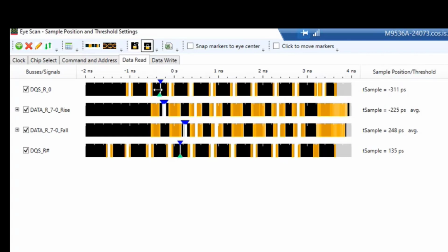This is a state measurement setup, and the strobes are going to look like a flat line in state mode since they're being sampled once per clock cycle. But they're very handy for timing zoom. You want to make sure that the threshold's right, and you can see that you've got a preamble and then the 8 samples. This is read, so the read strobes are straddling the eyes of the read data.